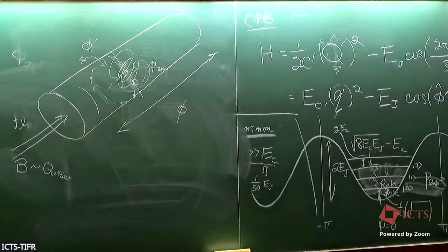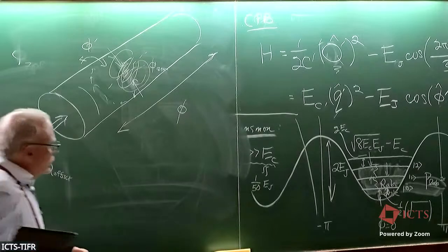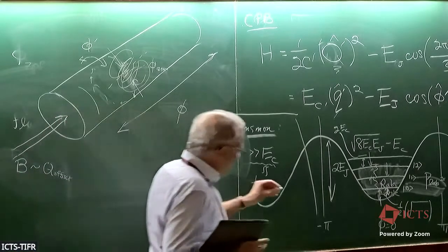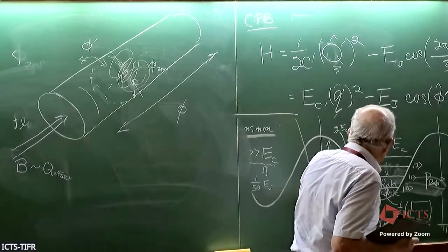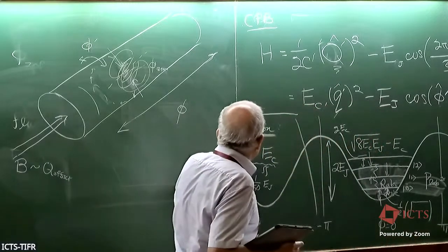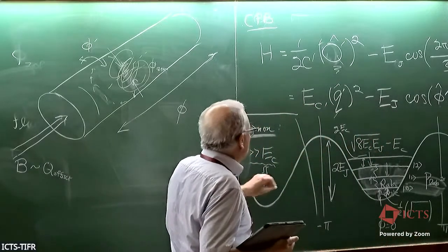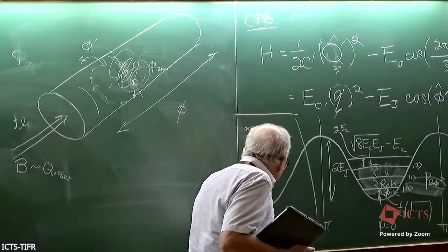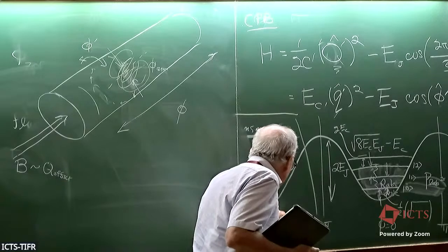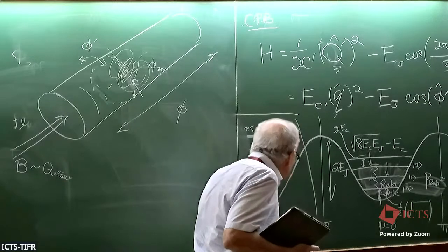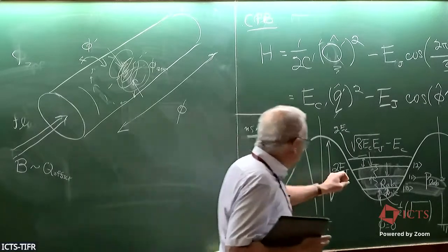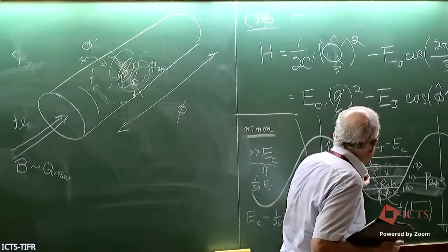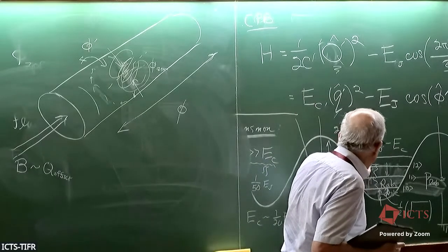But it was a real struggle, and what has mostly been seen, in some very beautiful experiments, is that you work in regimes where you're high in the spectrum, or you take EC to be maybe 1/20th of EJ, so you're now far in this transmon limit. And then you monitor the position, say, spectroscopically of one of these levels, say this one.